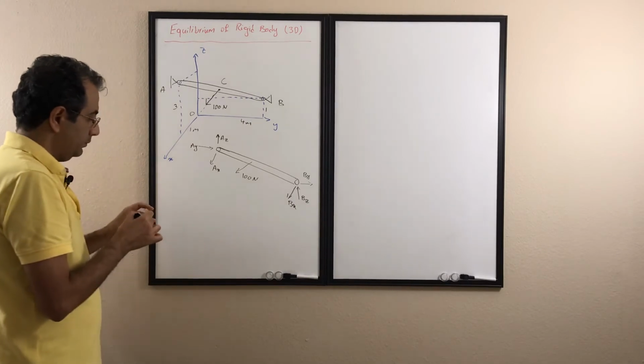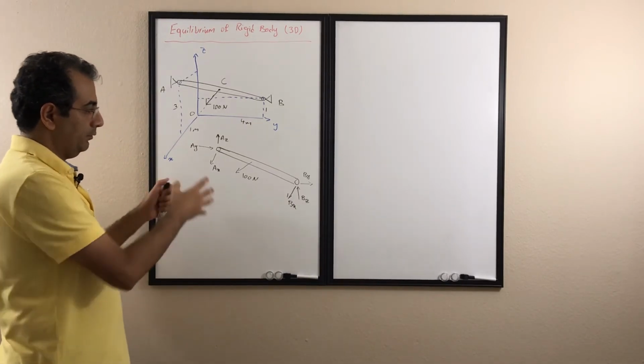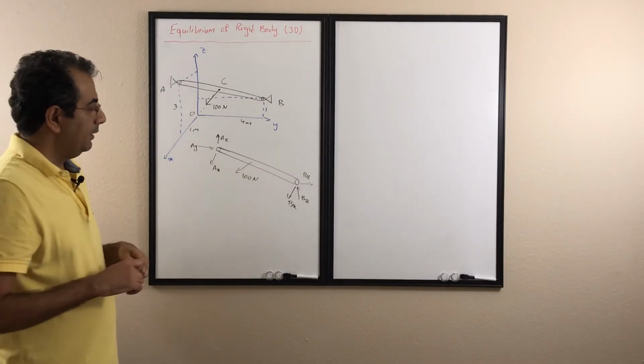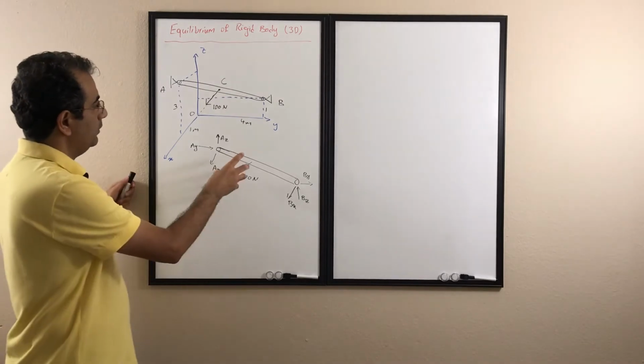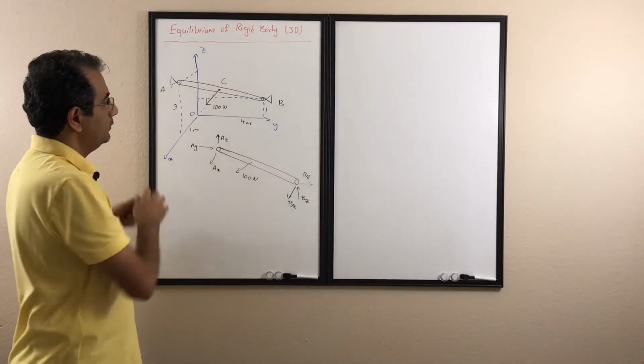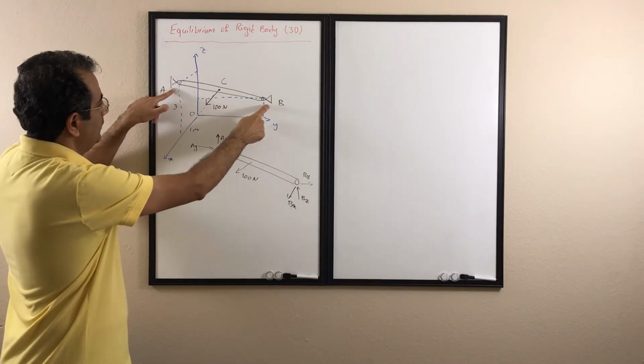So this is my free body diagram. So I have all the external forces. I first disconnect the part from any connection, and then I add all the external forces. One of them is the active force, that 100 Newton, that is pulling it down, and then there are the two supports here holding it in place.